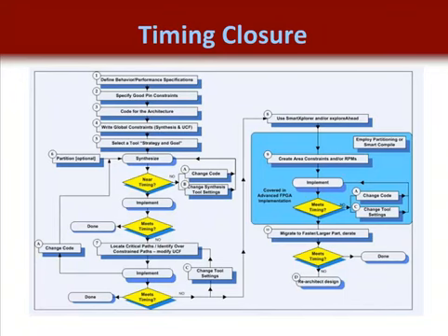After fixing the design, most customers should consider using their synthesis tool to full advantage, and that's what we're about to go into. And after resynthesizing with different options, perhaps even synthesizing multiple times with different settings, most designers then complete their first implementation. So keep in mind that using just a single set of synthesis options may not be sufficient. After reviewing this module, you should be able to anticipate which of the provided synthesis options might work best for your design. And of course, your results may vary because every design is different.